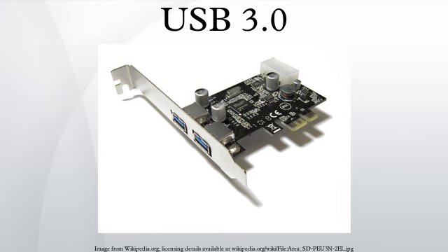All data is sent as a stream of 8 bits which are scrambled and then converted into a 10-bit format. This helps to reduce electromagnetic interference. The inverse process is carried out at the receiving end. Scrambling is implemented using a free-running linear feedback shift register. The LFSR is reset whenever a COM symbol is sent or received.